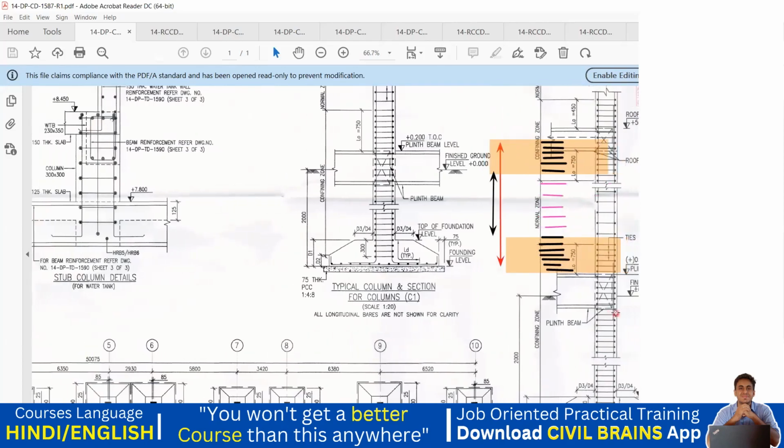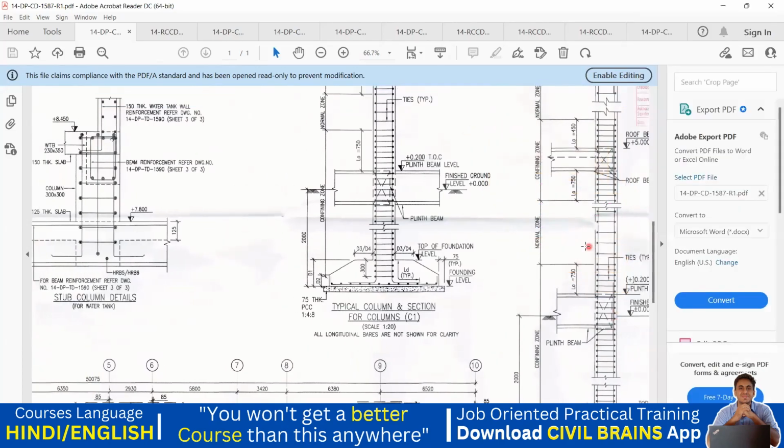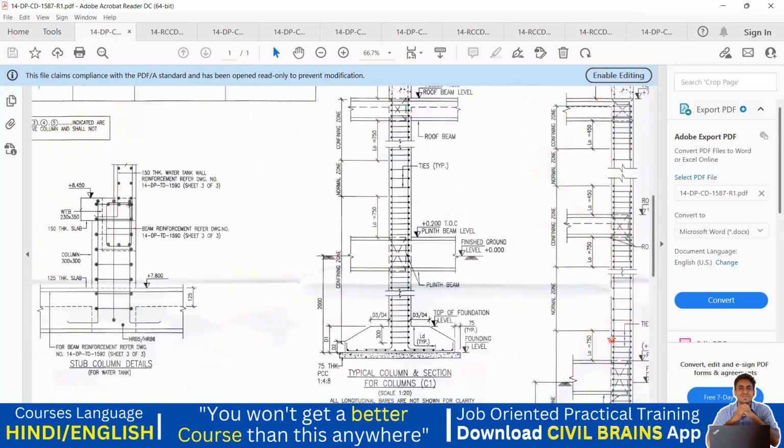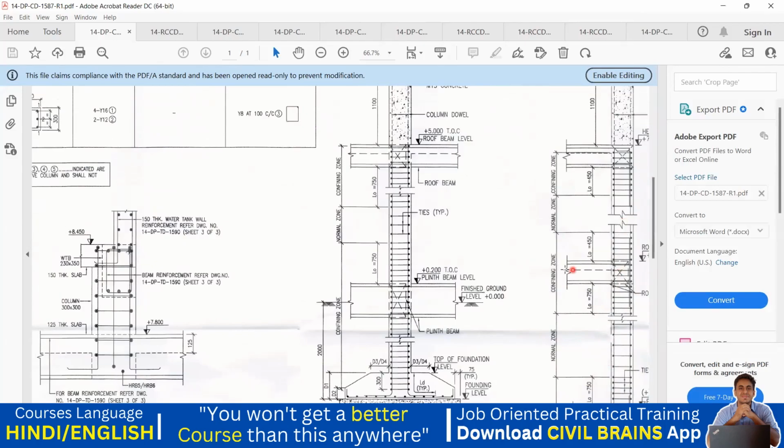Yeah, I'll go to the top. We can delete everything. See here also it's the same thing. Like if I come here, see, this is the top of the slab and this is the bottom of the slab. From here to this distance and from here to here distance, it is the confining zone. Okay, and your middle zone is a normal zone.